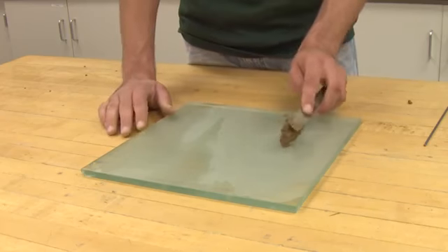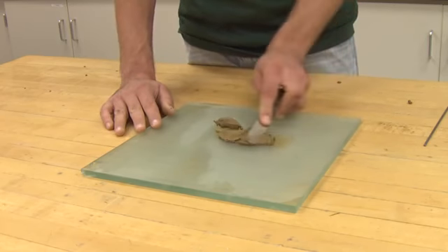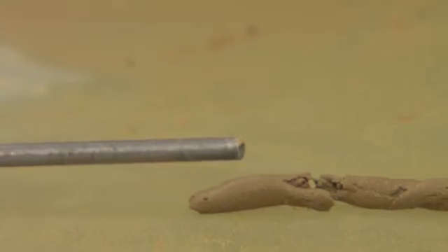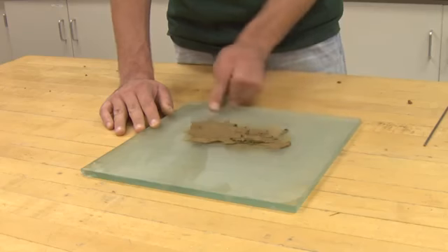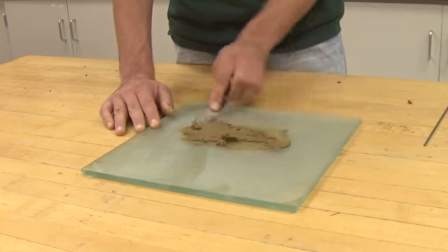We will need a glass plate to roll out our 3 millimeter threads on. We will need a rod that is 3 millimeters in diameter to gauge when we get down to 3 millimeters. We will need 2 cans to get moisture content in, and we will also need a spatula to spread and dry out our soil. The documents pertaining to today's lab can be found on Blackboard in PDF format.